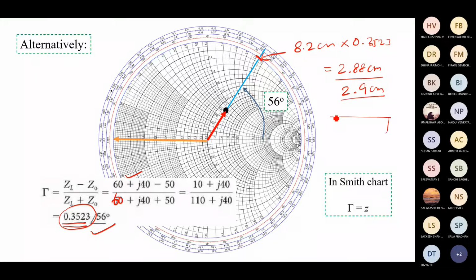In the scale, you take a compass, choose the center point, and with respect to that you draw the circle. This circle is what we refer to as the VSWR circle. It's not very perfect, but this is how we have to draw the circle. Now we have drawn the circle, and any one point on this circle is going to be the final reflection coefficient.